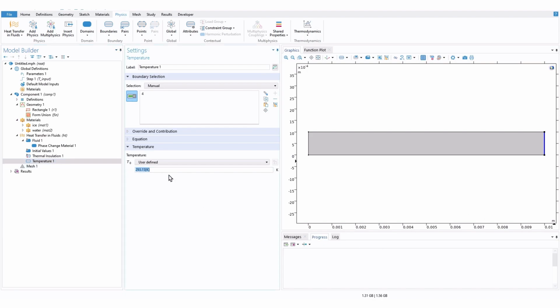So we'll just paste, and within brackets we can write t, that is the time by default in COMSOL Multiphysics, and to stay consistent with the unit we will write 1/s. Okay, so this is the format you generally use to write the time dependence and also to keep consistency with the unit. So we are almost done.